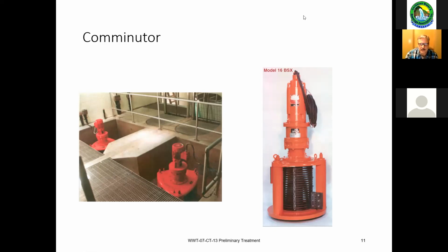All right, so the comminutors are bar screens, you know, they basically cut and grind material, making it smaller so it'll flow through equipment. This would be in a treatment facility. Cutters, you can see the blades on the machine which rotate. They pass through this attached cutter, and then any material is sliced from larger pieces into smaller pieces. As we discussed, having those in a treatment plant, in my opinion, is not your best option.